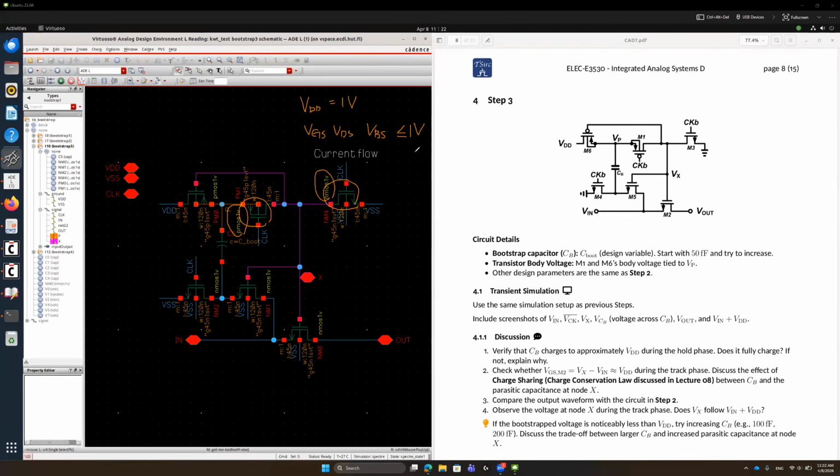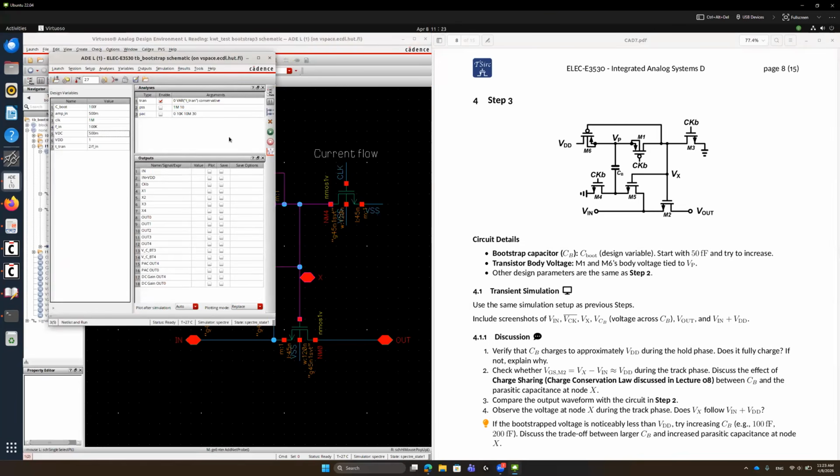Of course, for some safety margin, what foundry companies typically make sure is that it can safely operate slightly higher than the maximum supply voltage, for example 1.1 volt. But if we drive 1.5 volt, we cannot guarantee that the transistor operates correctly and without damage. So that kind of consideration must be taken into account, and here let me run the simulation.